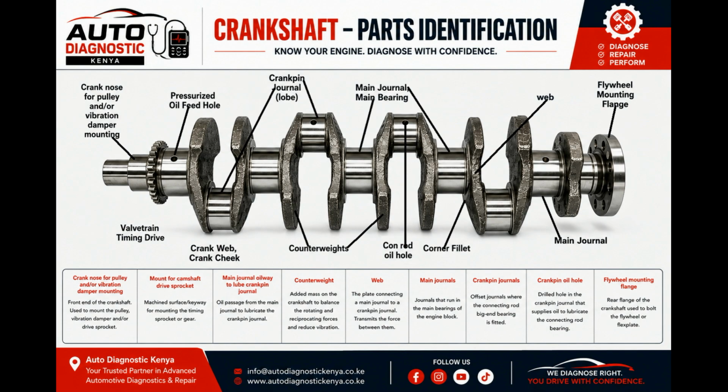Now let's speak of the crankshaft oilways. This is one of the most important parts of understanding the crankshaft. The crankshaft is rotating at high speeds, and the crankshaft journals are operating against bearings under very high loads, so they need lubrication. The engine oil pump sends oil under pressure to the main bearings.